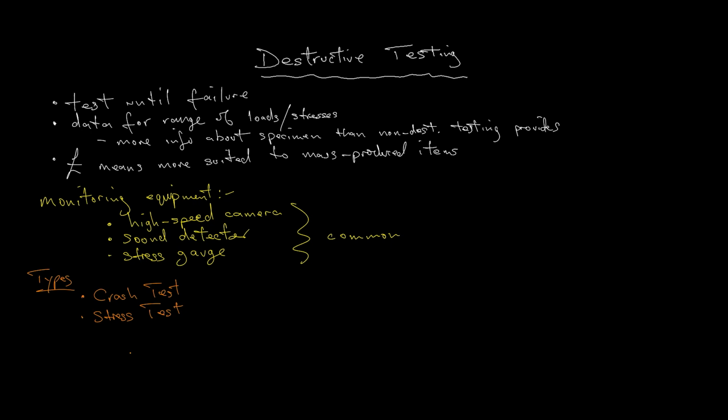Who knows? We can do pollution or corrosion test. Okay, so how's the thing going to behave when it's within the environments it's designed for? It could be designed to be in acidic environment, so therefore we're going to possibly use a long period of exposure to the acid or the corrosive environments, etc., and keep it going non-stop until the item fails, because this is still destructive testing.